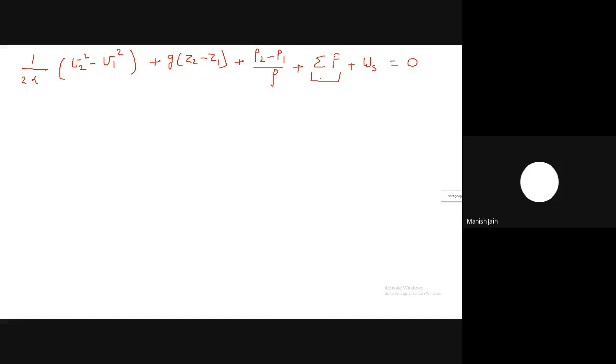Whenever you solve any problem related to fluid mechanics, when the fluid flows in the pipe, the first thing you have to calculate is the Reynolds number, because the Reynolds number tells you which region the flow is in, the laminar region or the turbulent region. Based on that, you can define the value of alpha also, and the other parameters can also be calculated from that.